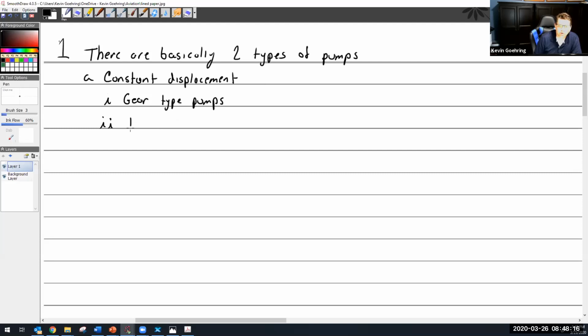And then we have rotary vane. I'm not aware of any gear type pumps that move fuel at all. Gear type pumps move oil and hydraulic fluid, but not fuel. I think the reason is that with gear type pumps you're talking about lower volumes and higher pressures, and rotary vane pumps can still do some higher pressures, but are much higher in the volume world for their weight.